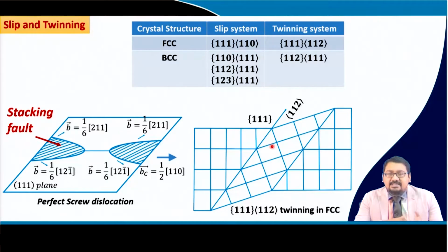And as I said in the previous lectures, twinning is a displacive mechanism, and it is not a diffusion controlled or thermally controlled mechanism, right. Now, of course, twinning may occur also in case of static annealing or under thermal activation, which includes diffusion mechanisms. Now, because the twin boundary is a fully coherent twin boundary.